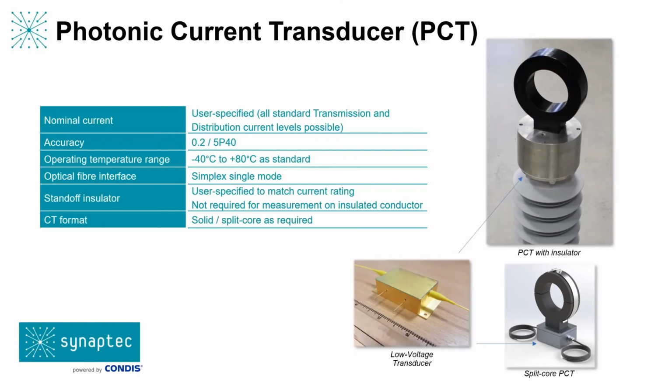And if StatNet wanted to upgrade the protection hardware in their network, they wanted to know if they could do it with less equipment and with shorter scheduled outage times. Traditionally, if you're replacing the busbar protection hardware in a substation like this, you might schedule an outage that lasts 8 weeks. And the fact that we could retrofit one of our systems in 2 days and still work even with total or partial outages occurring within the substation because the sensors are passive, that's a huge benefit for the operator to reduce the outage time that's required to upgrade or back up the scheme.